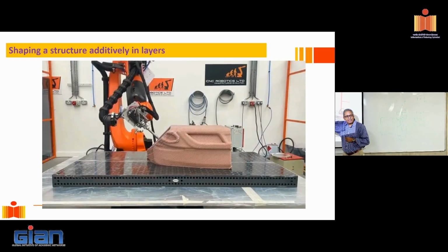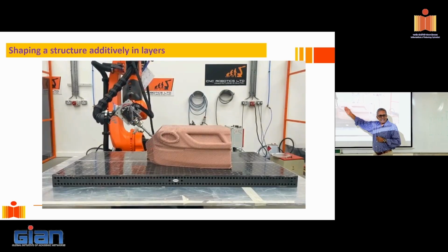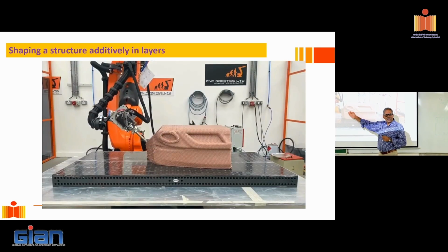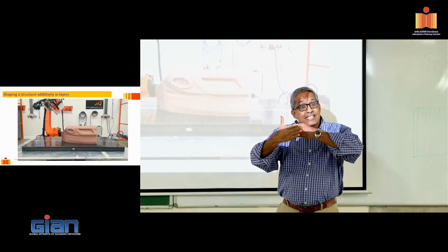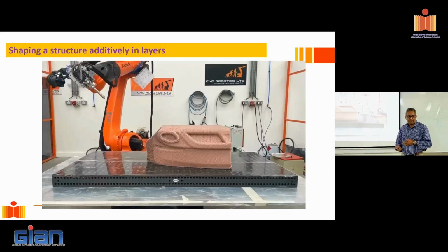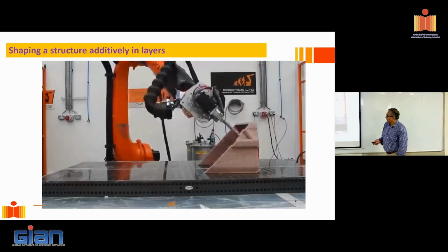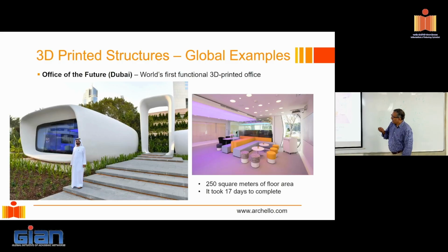It's not even cantilevering. They're cantilevering from here, right? And look at the stresses on the interface here. What would you see? This thing essentially would just slide off if you don't print properly. That means the interface, the shear strength of the wet interface becomes very, very important. But we can do these things if you actually engineer your material. Yeah, and just quickly run through this.